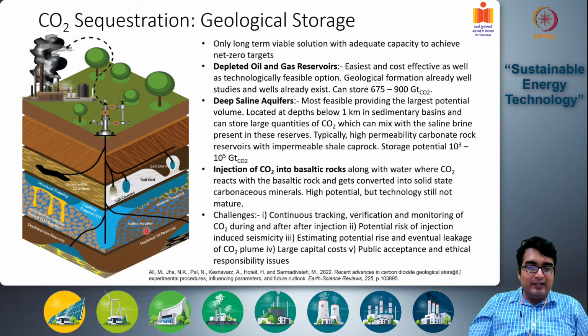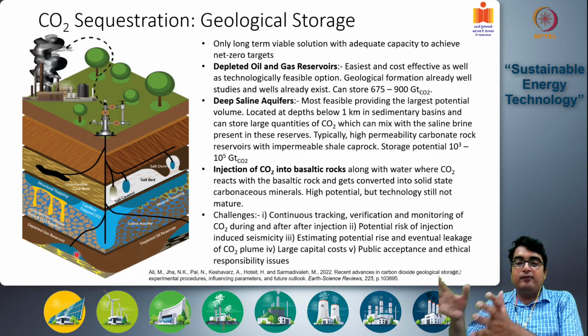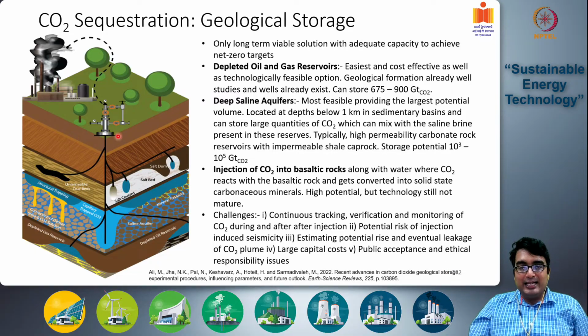So this is kind of a depleted oil reservoir, this is a depleted gas reservoir. You already have these wells in operation that originally extracted the oil and gas out of these systems. Now you are pushing the CO2 into these systems and filling up these reservoirs. Okay. Just as it had oil and gas before, it will continue to have the supercritical CO2 in these regions, and after it has all been filled up, we will close the wellhead to stop this CO2 from coming out. Okay.